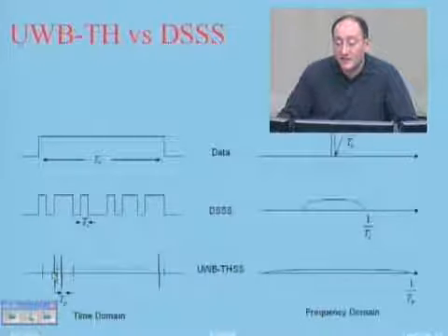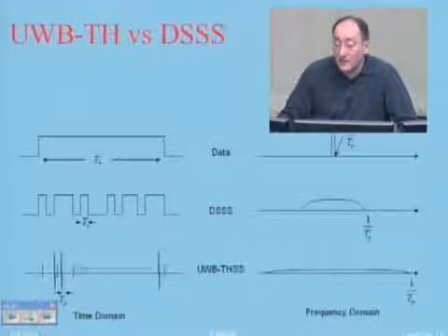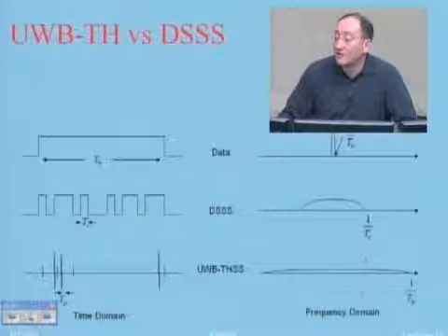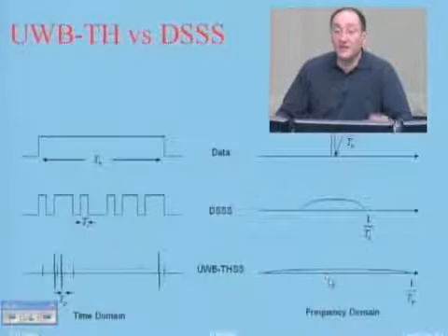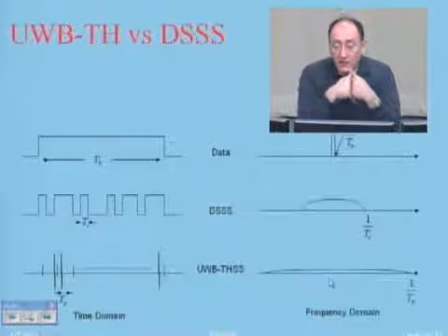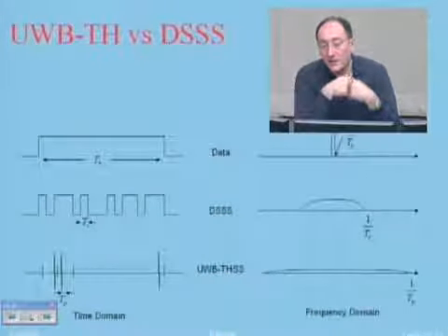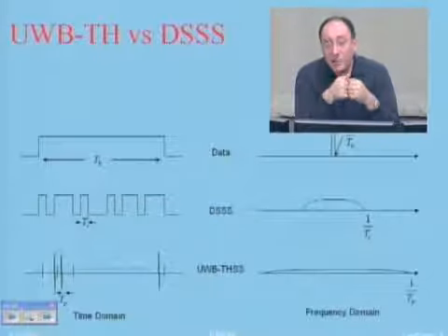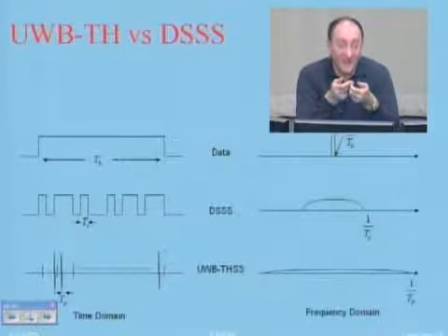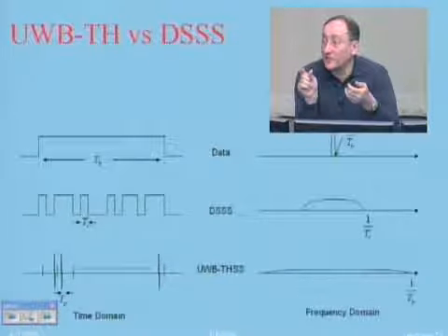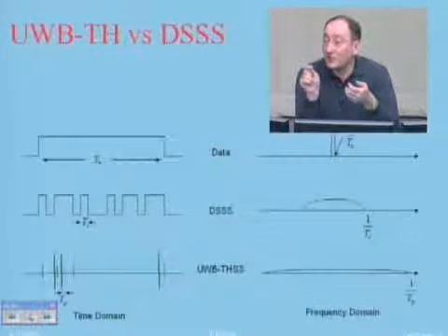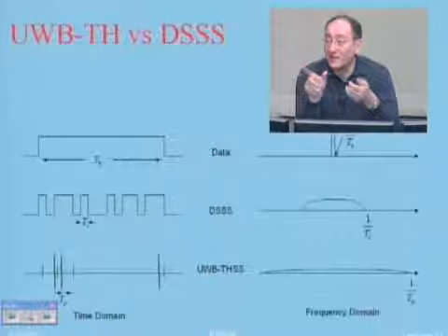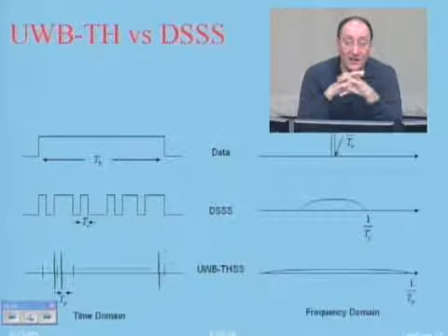In here, it's the inverse of this, which is like fractions of that, so the bandwidth is several times more than that. So ultra wideband is spreading a spread spectrum even further, because in each chip of a spread spectrum, I'm now sending a narrow pulse. That's why they call it ultra wideband.